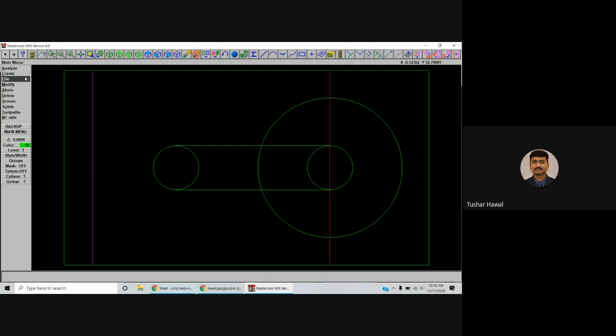For that, the reference is again a line at the center, from the central horizontal line at a distance of 24 on either side, that is top and down. I need those two lines of distance 14. So I'll create a big line in the initial step, and then I can trim the lines so that I can retain only the required portions. Then I can offset this line also, so that only the distance of 14 mm is maintained.